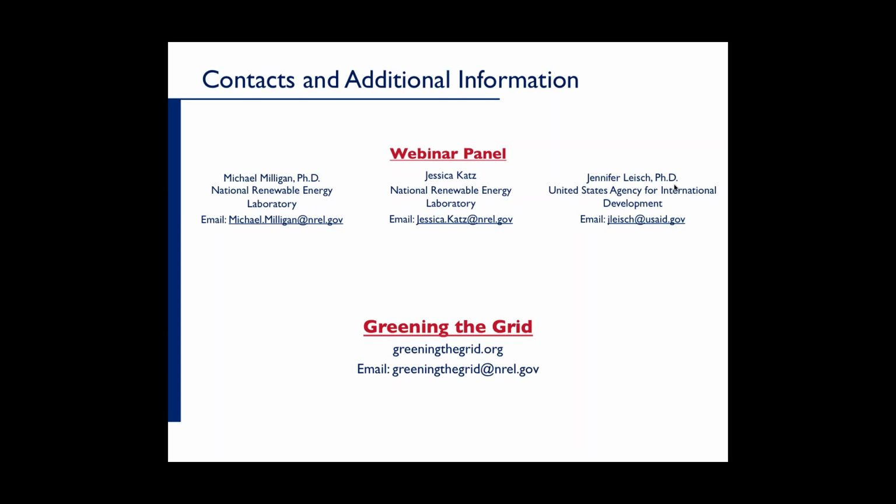And so I think one of the biggest challenges is to figure out a way for the distributed solar to be visible to the power system operator so that decisions on how to best operate the rest of the system can be made efficiently. The other issue can be, you may be getting some backflow from the distribution system to the transmission system, which isn't necessarily a problem, but again, you need the ability of being able to see what's happening and probably some means of controlling the PV.